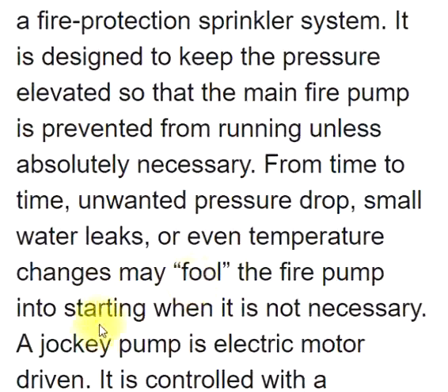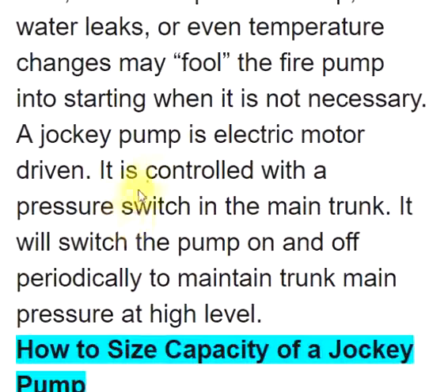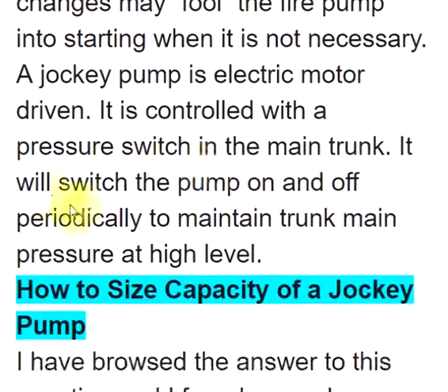A jockey pump is electric motor driven. It is controlled with a pressure switch in the main trunk. It will switch the pump on and off periodically to maintain trunk main pressure at a high level. How to size the capacity of a jockey pump?